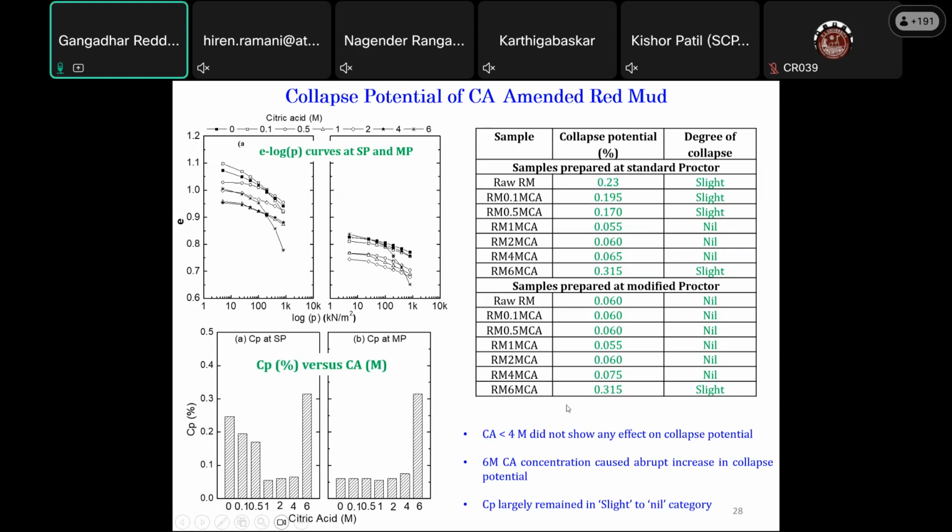So even when you are treating any kind of red mud, we need to monitor what is happening to the geotechnical properties. This is basically neutralization. After that, if you want to use it for any kind of application, we need to see what is happening to the strength parameters. It is not only about strength. What happens when it interacts with another liquid medium? We need to see that. So we always use a good amount of any kind of additive, for better application.